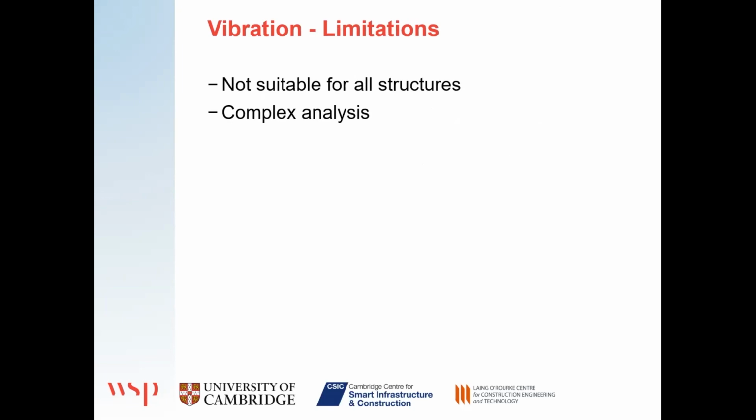Again, it's not going to be suitable for all structures. You need to be able to detect changes in the vibrational response. So it works very well for bridges with slender piers, but not so well if you've got sort of large masonry structures. And it can be tricky, I think, to relate the changes in vibrational response to an actual scour depth. So although you can tell that there is a change, setting a threshold beyond which you've got a problem is not always straightforward.